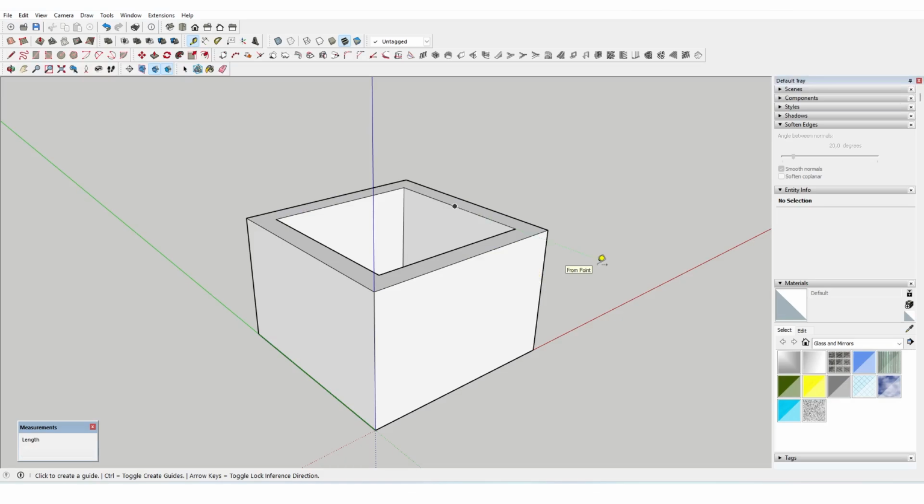There are two other little features that are hidden within this tool. One is a guideline. Now, to do a guideline, you will hover over a line that you want to do, which will be essentially snapped to the specific axis. You'll click and drag. Now you can type the increment you want, or you could just drag it to the point that you feel like you need it to be on. So for now, we'll do an increment so that we can get a specific size to put a hole through this box.